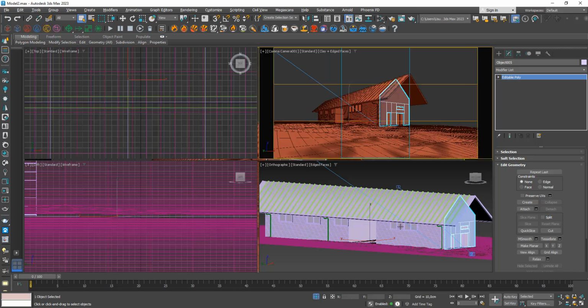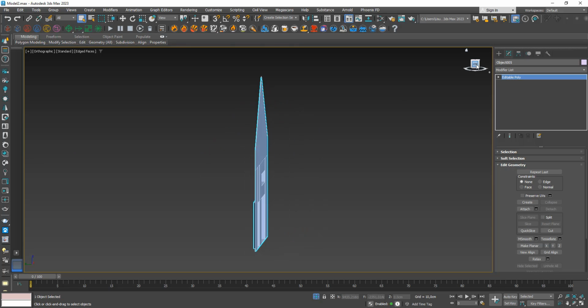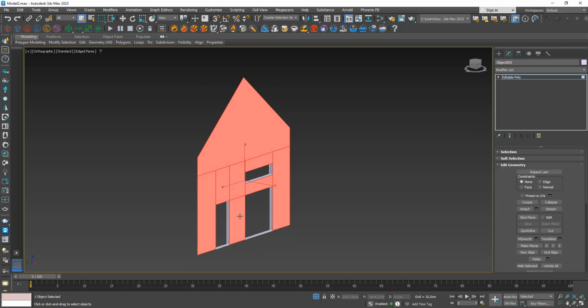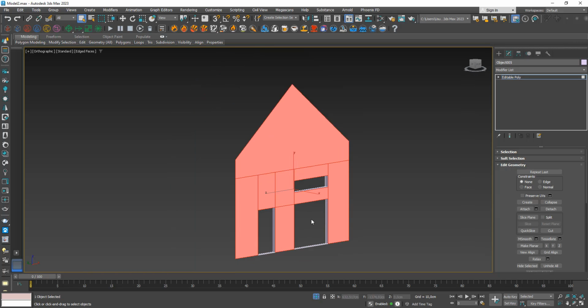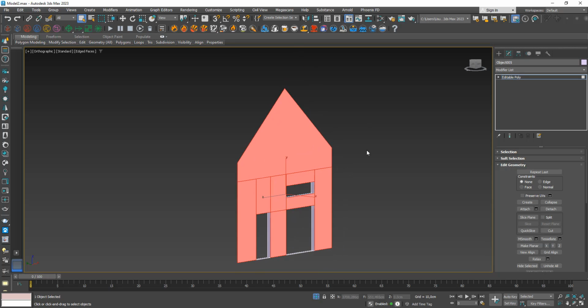Now let's go ahead and select this face, Alt+Q, and we're going to be doing the same thing. So how does the floor generator work? It basically needs a flat surface, so that's why I'm excluding these extrusions that are inwards. So I end up with this plain surface. Now let's go inside the edit geometry and detach it.